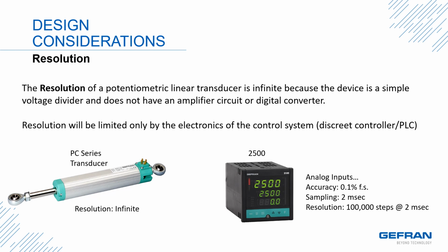You'll also see a picture of our 2500 series controller. Although it is very, very good, the resolution is not infinite. The specification on the analog inputs are an accuracy of 0.1% for full scale, sampling of 2 milliseconds, and a resolution of 100,000 steps at 2 milliseconds.